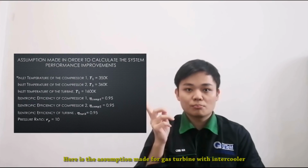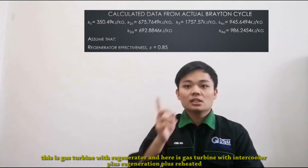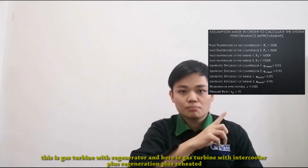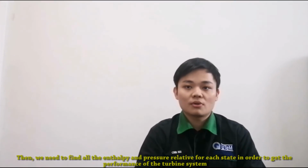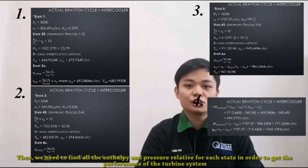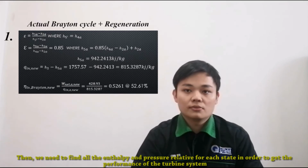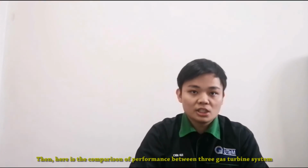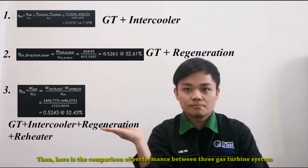Here is the assumption made for the gas turbine with intercooler. This is the gas turbine with regenerator, and here is the gas turbine with intercooler plus regeneration plus reheater. Then we need to find all the enthalpy and relative pressure for each state in order to get the performance of the turbine system. Then here is the comparison of performance between the three gas turbine systems.